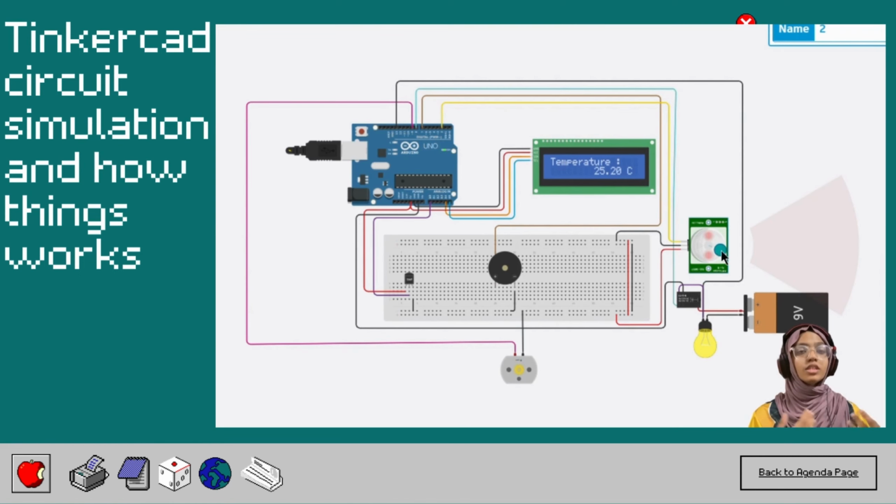After that, the system also checks for motion using the PIR sensor. If motion is detected, it will light up a bulb and at this point switch the relay to the battery pack momentarily before switching back to the main power supply. The relay is used to switch the power source, connecting either the battery pack or the main power source depending on the input.